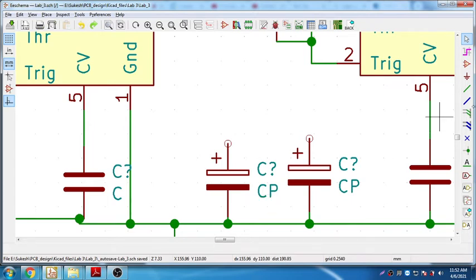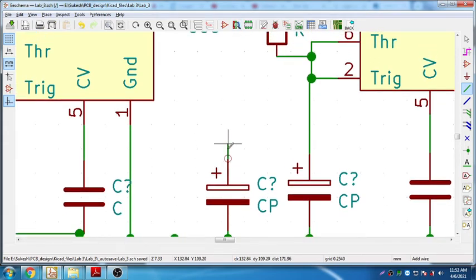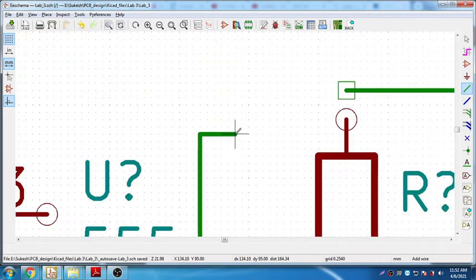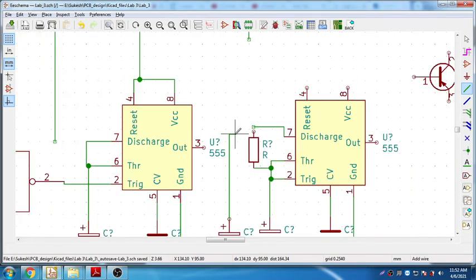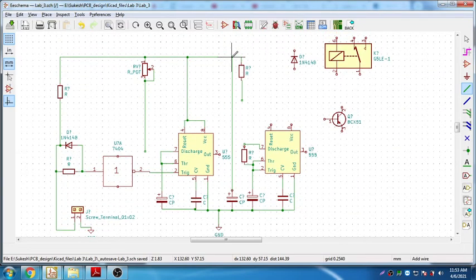I'm going to connect this capacitor to this point. Okay, then this is supposed to be the capacitor connected directly to the power, so I will connect it here. I think we can have this connection later also. Okay, it's connected straight away to the VCC. Fine. And if you see here, pin number 3 is connected to pin number 2.